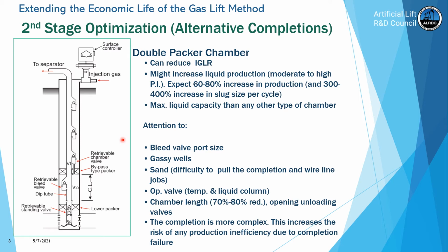I've been in many places around the world, and they have told me that they don't want to do this type of completion because they tried it in the past and it just didn't work. Well, I did a complete troubleshooting analysis in Lake Maracaibo one time, and there were 10 wells there, and they were not producing. The increase in production wasn't there. In fact, the injection gas liquid ratio went up.